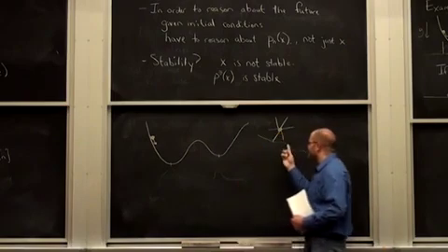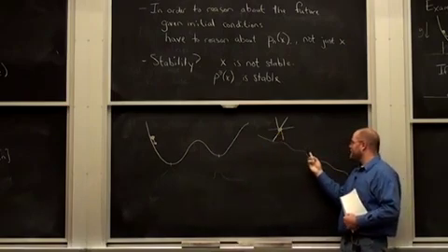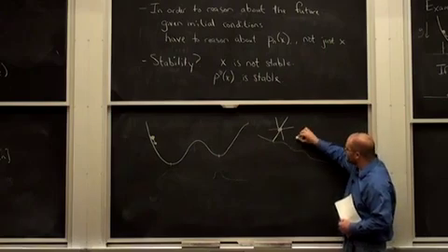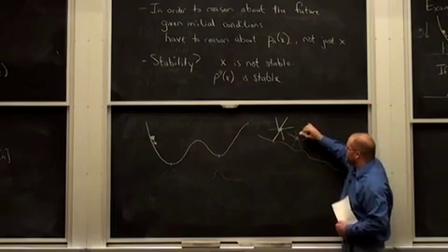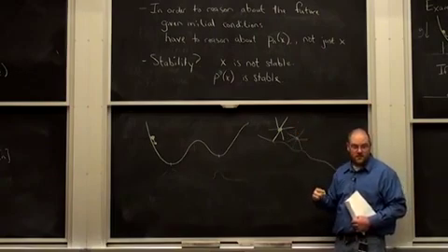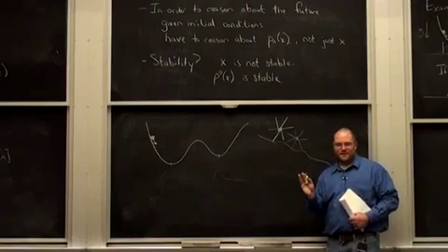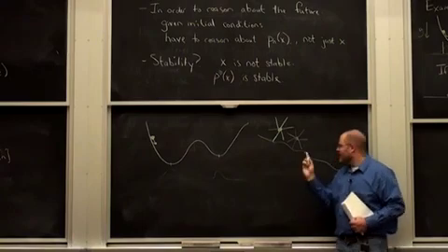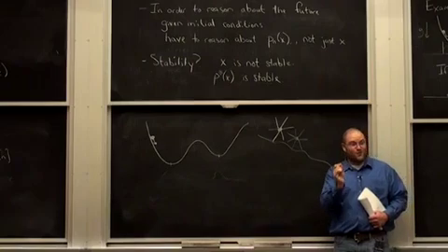If I look long enough, this thing has an absorbing state. If I take a big enough step, then eventually I'm going to lose enough energy. Remember, the deterministic system had two fixed points. One was standing still, the other one was rolling at a constant speed. The standing still fixed point on rough terrain is an absorbing fixed point. If I get there and I never take another step, then I'm never going to leave that fixed point. So that is actually a true fixed point.